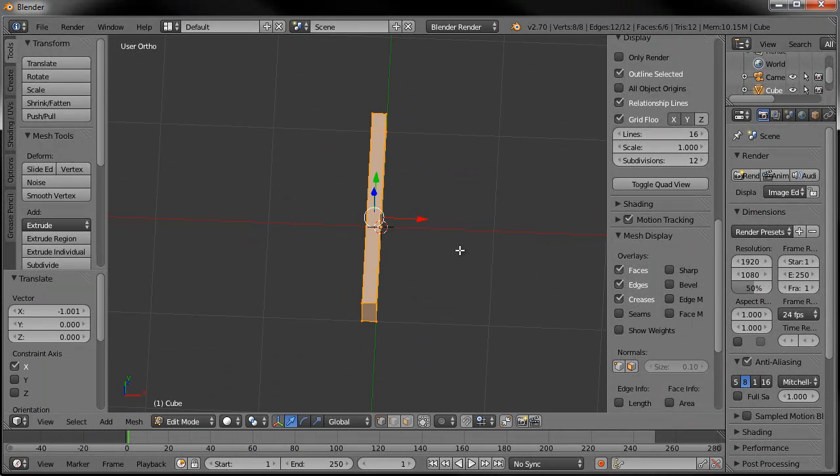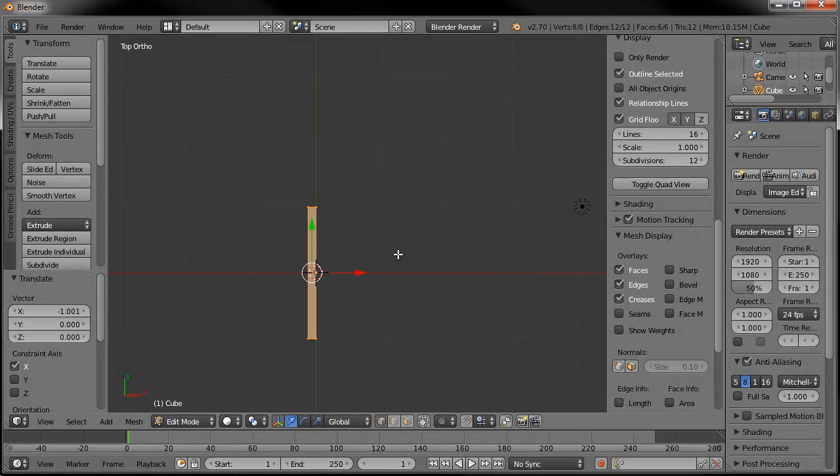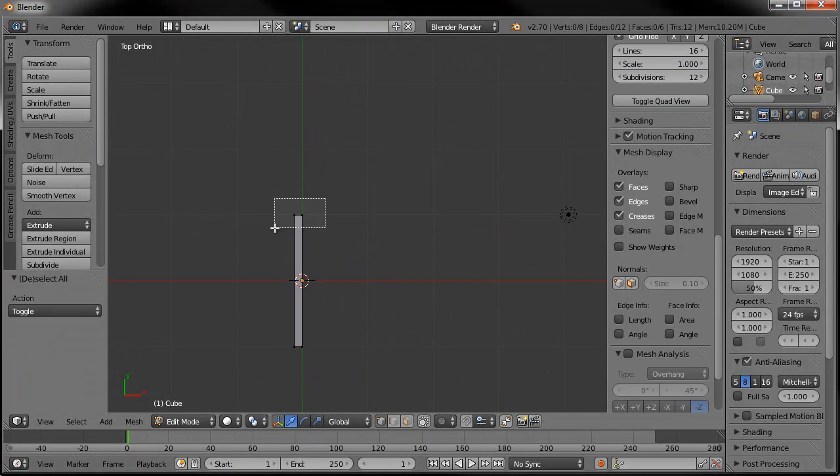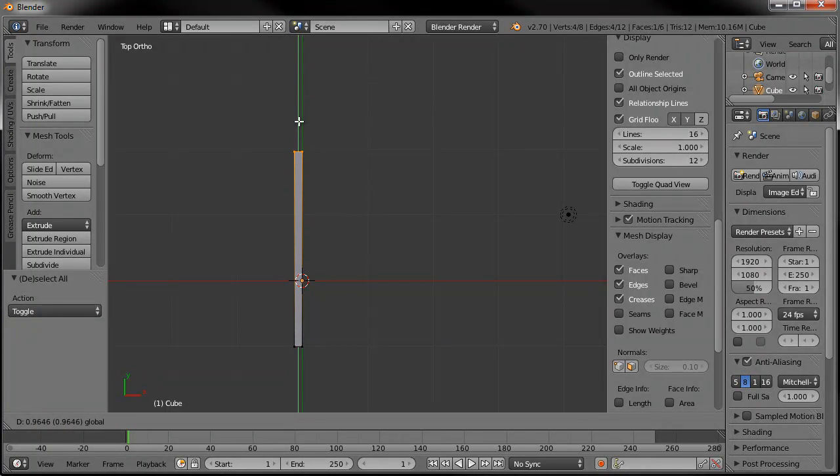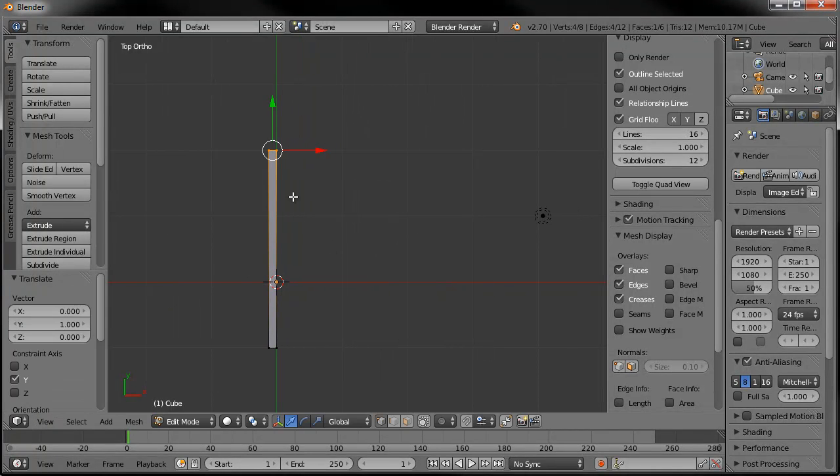Now, okay, so the box I want to build for the planter, I want to make it 3 feet by 1 foot. So let's grab this and drag it up another foot. If you hold down Control, you can increment up inches wise. So that'll help you keep things accurate too. So let's select this, Shift D. I'm going to duplicate that.